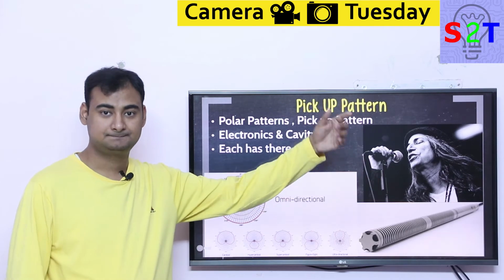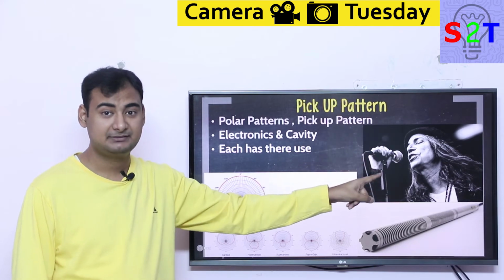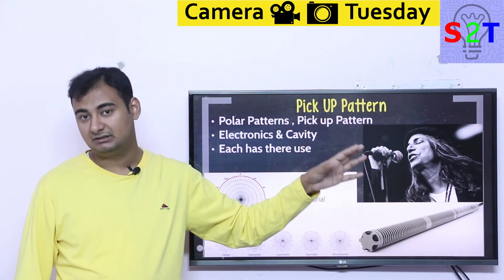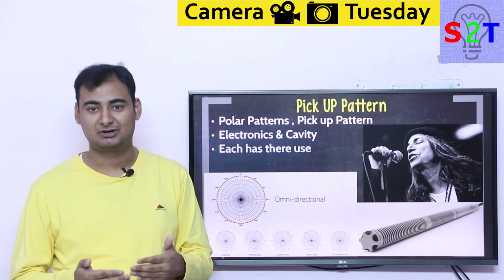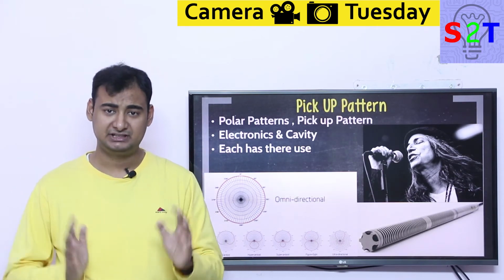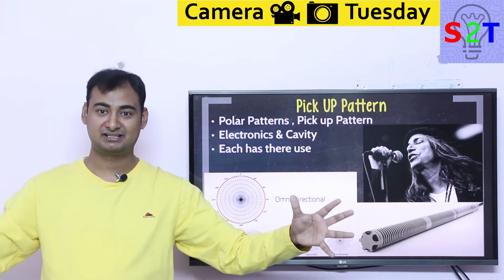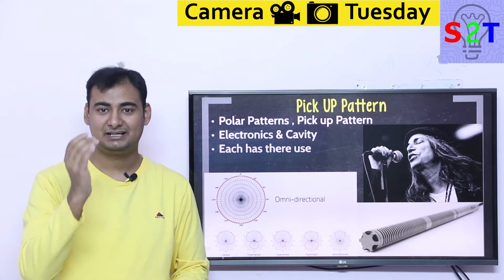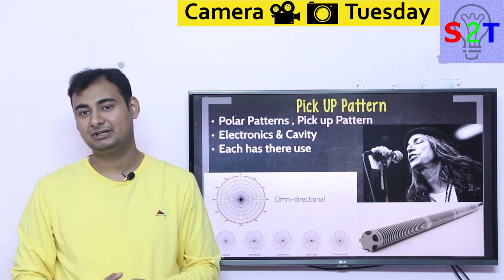This is a dynamic microphone. Not this exact model, but many times people use a dynamic microphone because it has a very unique pickup pattern, and that's how that singer is able to be heard. I already told you the decibel scale is kind of odd, so that singer or whatever talker you have will barely push 100 decibels of sound. When he's screaming he will barely get to 120 if he's trying really hard and wants to die. But when you have a lot of audience in front and giant megawatt size speakers blasting sound at them, this area is much louder, like 120 decibels. How can that microphone pick up 100 decibels on top of 120? It does not. That is why we worry about pickup directionality.